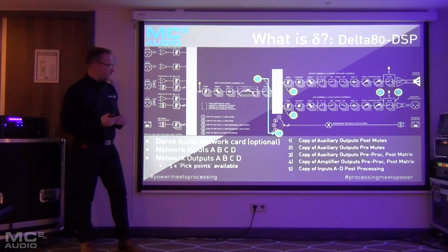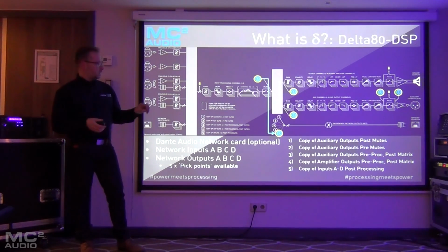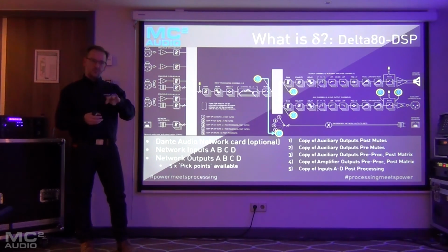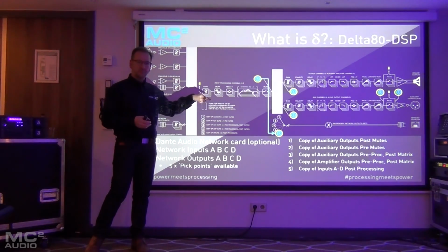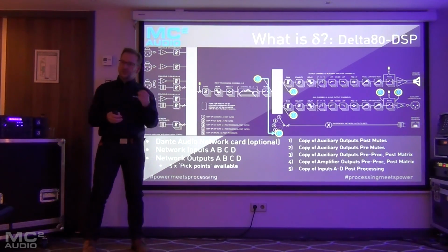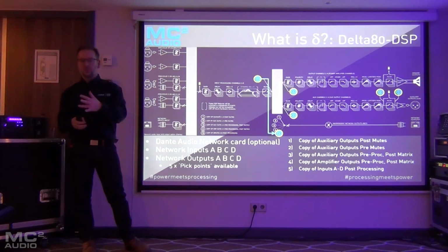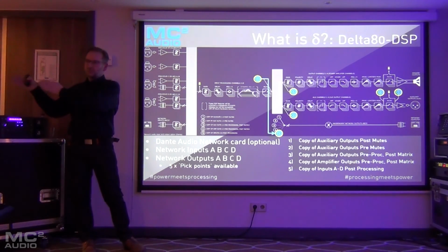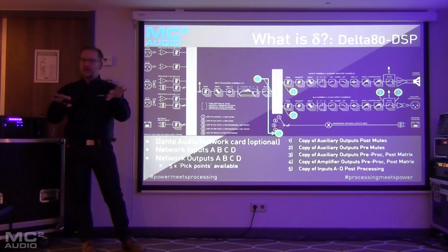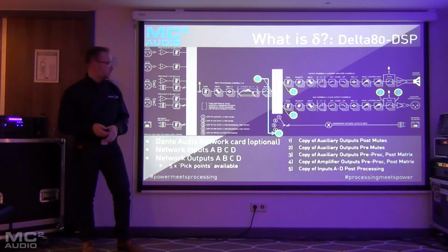So one important thing probably to note here is that you can only switch the 4 Dante outputs in blocks of 4. So all of them will be sourced from the same point. You can't choose point 1 for one channel, point 2 for a second channel, point 3 for a third channel. So all 4 switch as a bank simultaneously. There's no mix and match as far as those output points are concerned.